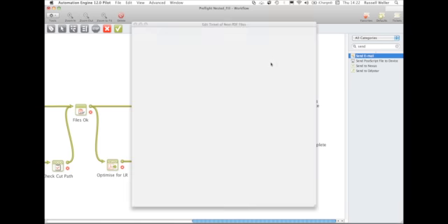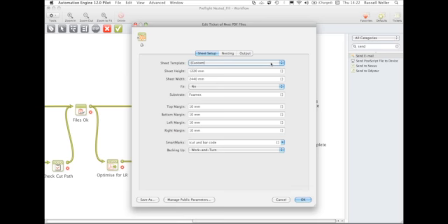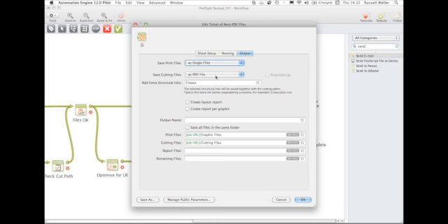And then it's through to the last stage of the process in this particular workflow, which is then going to go and lay out my particular files. Notice we can start putting in substrate information, so Dibond, Foamex, whether it's on corrugated, maybe it's going down for a roll to roll, so we can put in that particular banner material that you're working with. We can take sheet sizes through, and then from there we can start generating the relevant graphic file to go down to the output device, and also a multitude of different cutting files that you can see here.